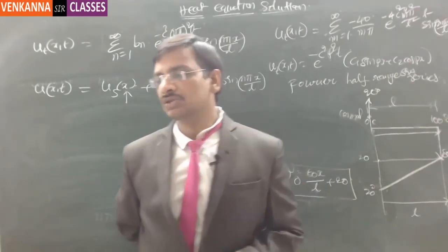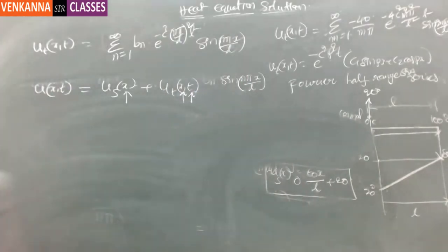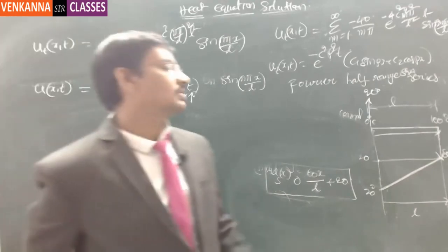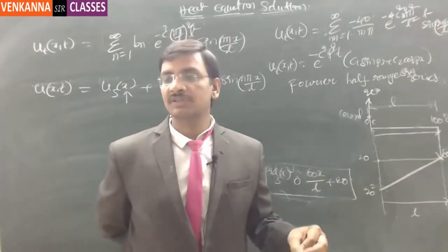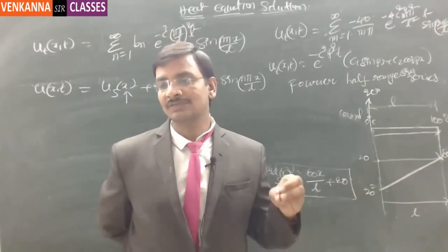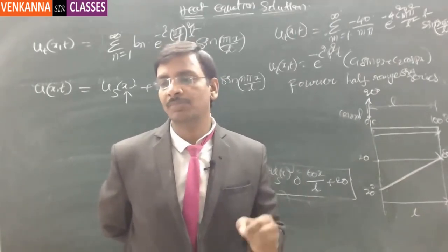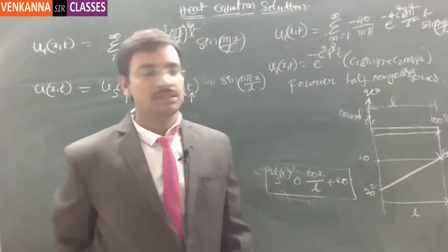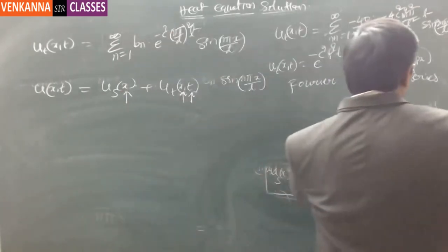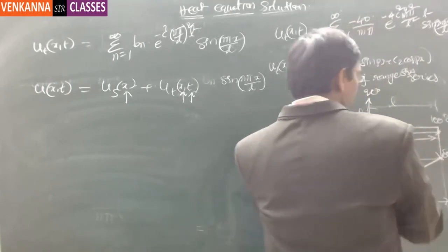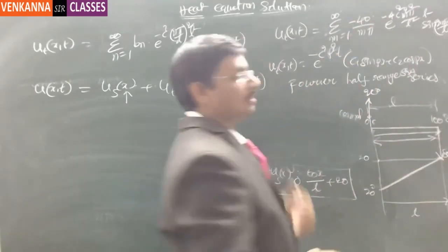By the transient solution we mean the changes that are happening, while the changes are still running, with respect to time. But in the steady state solution, it is independent of time and depends only on the space coordinates. That means the temperature you are going to see here depends only on the length. It doesn't depend on the time, right?